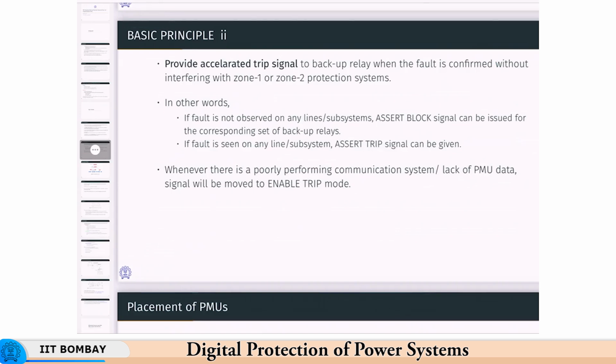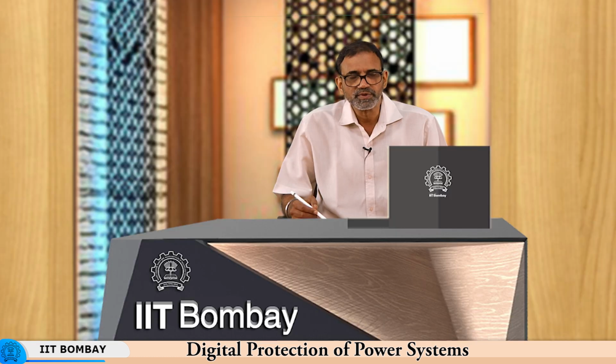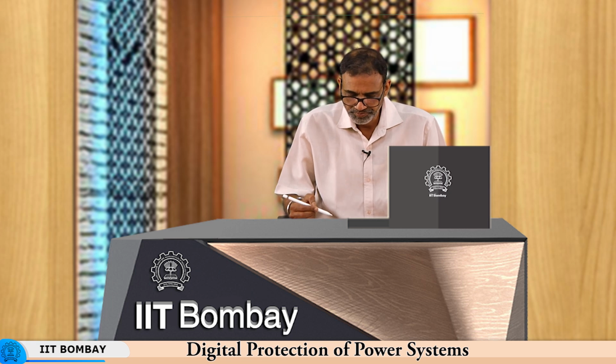Okay. So, the principle is that since the zone 3 relay has a greater delay, which we saw is anywhere from 500 to 900 milliseconds, if you can confirm that there is no other abnormal event and this relay has picked up only due to fault, then we can give an accelerated trip signal also.